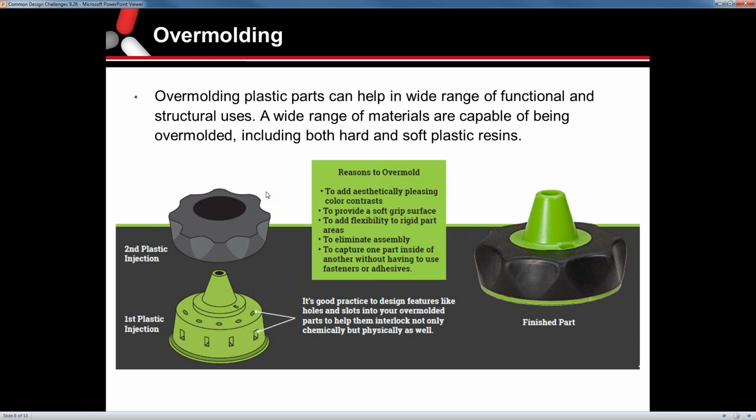Okay, looks like we got another one here. Can you explain a bit about what the overmolding process is or how it's done? Essentially, you're taking a substrate, which is usually going to be a more rigid part. Could be a polycarbonate or an ABS or nylon, and then overmolding a secondary material on top of that. The way we do it here is a manual process, like an insert mold process, where we'll process the substrate first and then load that into a secondary tool and shoot the second.